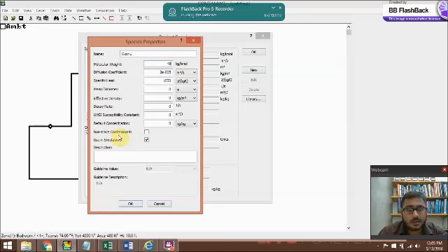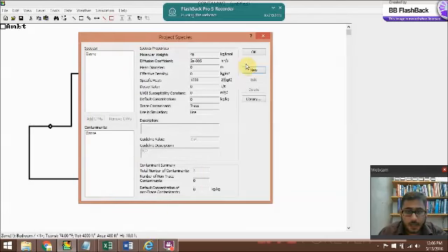The non-trace contaminants would be for something like water vapor, where you just calculate your humidity, and you'd have to do it using simulation so that it's calculating it. You can even set up the default concentrations if you know some minimum concentrations would be present in this space. If you can add default concentrations over here and even add in the zone, that would add up to the concentration. So make sure it's mentioned at one place.